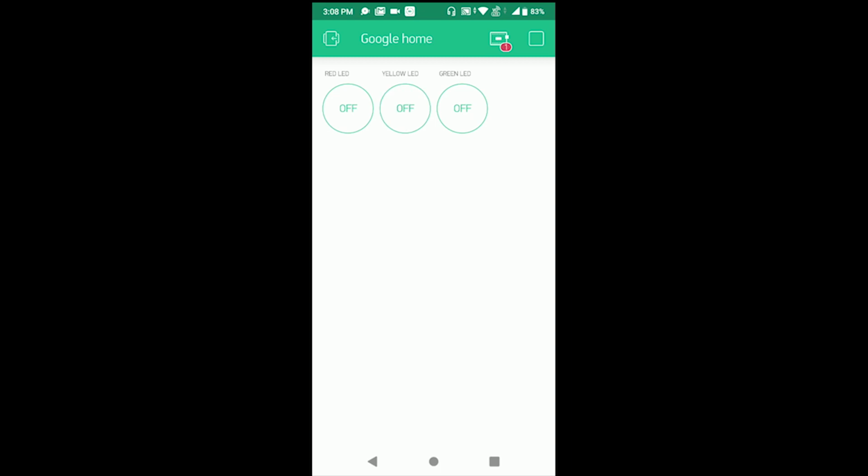Now I didn't configure anything in my NodeMCU, so nothing is going to happen. So if you look into this icon, like top right, you can see a controller board kind of button there, and it's showing an alert. So when I tap on that, it's showing Google Home wasn't online yet. That means my NodeMCU, my hardware, which should be connected to this Blynk platform, is not online.